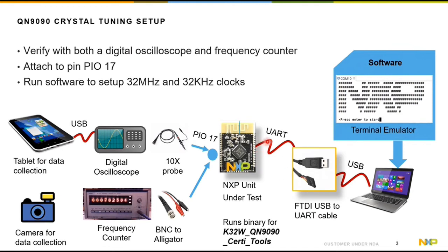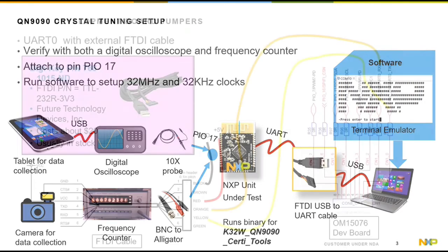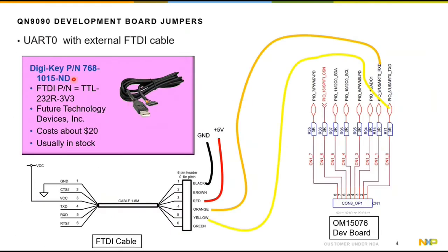But for the majority of the cases, I'm trying to figure out how to use this UART cable to FTDI. And so the common one, and I just listed one manufacturer and distributor's part number. It's a fairly standard cable harness connection. It's recognized in a lot of different literature, and it's going to be UART 0 on my device. So the pinouts and the colors again are pretty standard. It's on a 0.1 inch header. You may have a DB9 connector on here, or you have to go from this header to a DB9 connection.